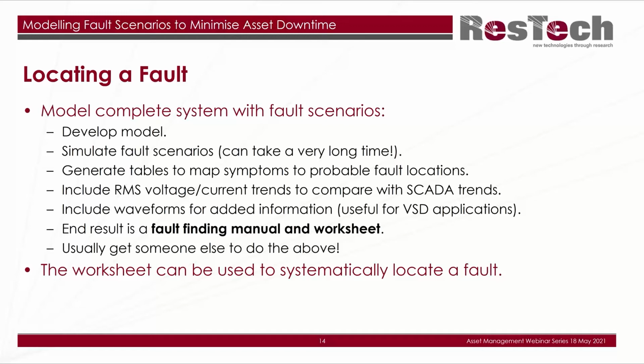Now of course, when this is done, we don't necessarily get a unique mapping. You might find that as we do the scenarios, a few scenarios might map to the same set of symptoms. But what that's done is basically narrowed down a large set of possible causes to maybe 2 or 3, which makes the debugging a lot easier.